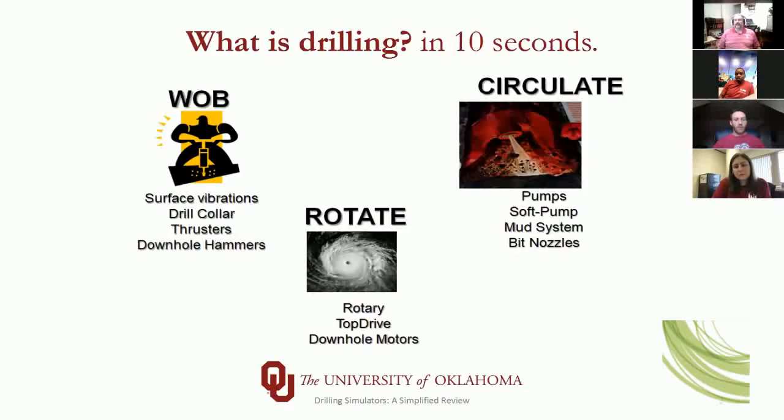How to drill a well, and I will try to do it in less than 10 seconds, which is very simple. Drilling requires 3 major things. You need weight on bit, you need to rotate, and you need to circulate. This is the science that was invented in 1901 at Spindletop, Texas, by drilling the first well applying this process. What has changed from 1901 to 2020?